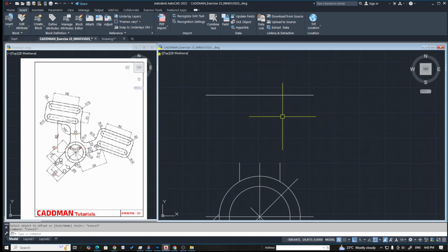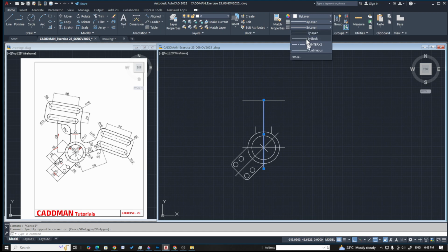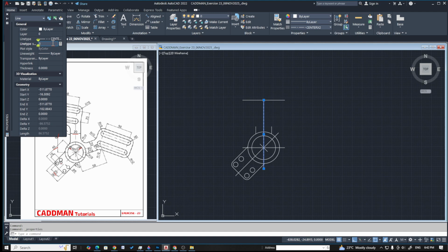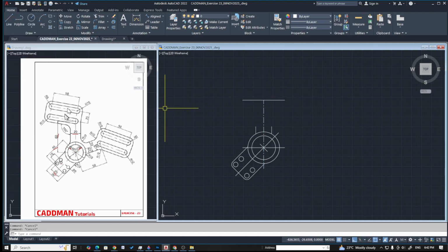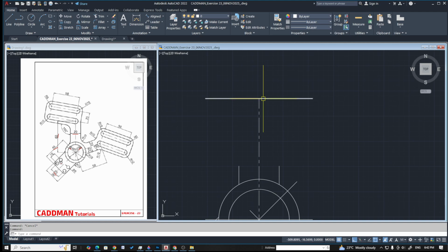So this is where, and this is our center line. Let's try to change this from solid line to center line. So here lies on the center of this line at a distance of 60 to this endpoint lies this radius 5. So let's try to